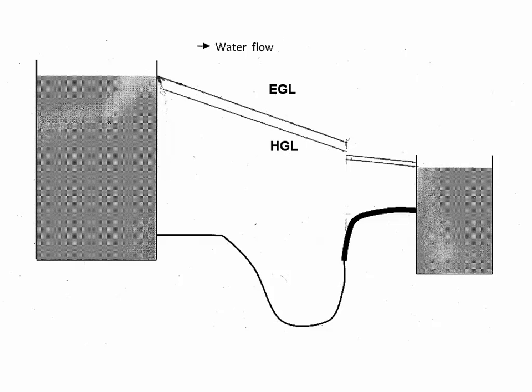Yes? The part that looks like there is a turbine or something, where it goes down, I don't get why. Oh, this? Yeah. It's because here we have a local loss. The water is going from a small diameter to a large diameter pipe. So we talked earlier in the class about K values. And so this drop, you're right, a turbine does the same thing, but in this case it is a sudden loss of energy because of the transition in the pipe diameter.